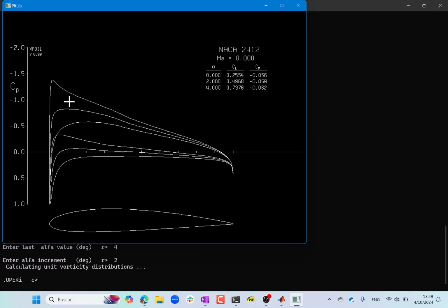There is actually a trick part of the question in it. If you have a positive camber, no NACA 4-digit airfoil is actually going to get you my answer. You actually have to flip it. And the right way to flip it in this setting is you want it to generate negative lift. So try to think in the context of generating negative lift and see if you can get a lift right at the leading edge. If you already got it, you're free to leave.